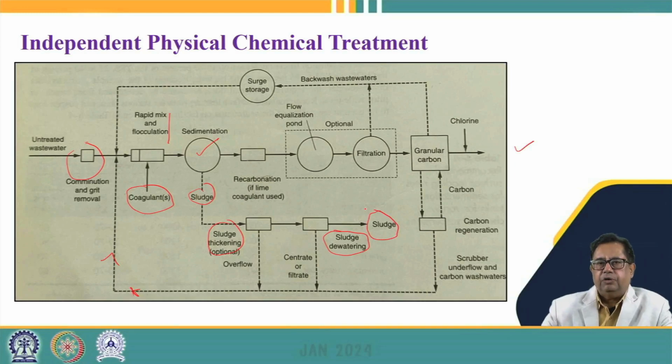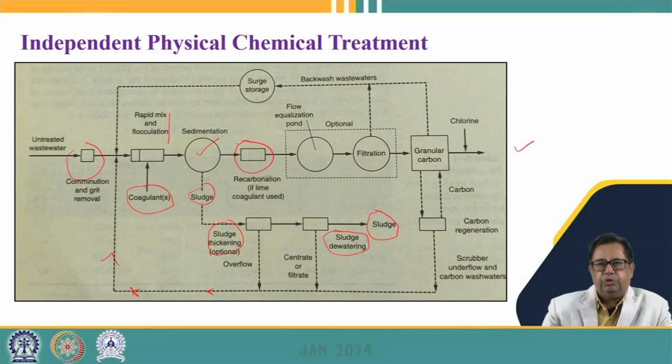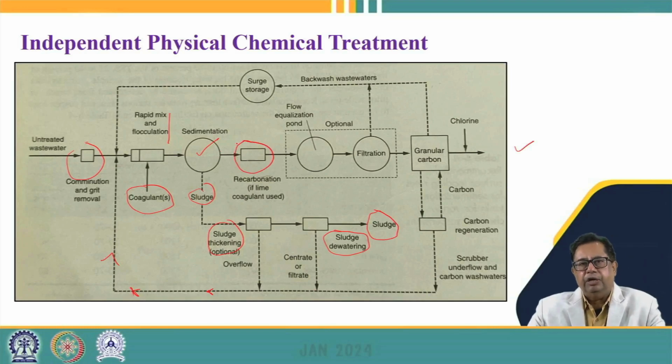The treatment and handling of the sludge we will discuss in detail in the next module. And here, whatever filtrate comes out from the sludge dewatering is also taken back to the influent. After the sedimentation process, we may go for a recarbonation process, where we add carbon dioxide.